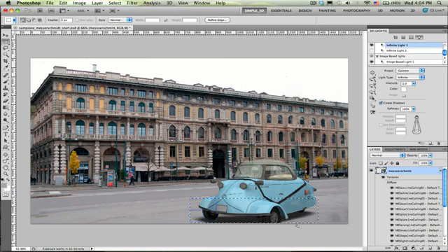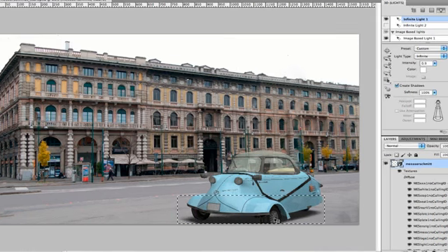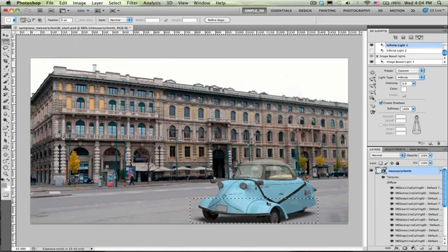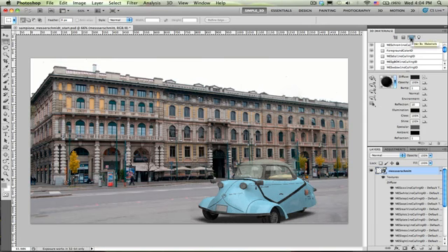Now the other thing that I want to fix for is the reflections. Notice that in this image, everything is reflective. The tires are reflective, the car is reflective, the roof, etc. And I want to change those properties. For one, I don't want my tires to be reflective. That's not very realistic. So up here, in my 3D panel, the third filter is my materials tab, and it's going to filter and show me all my different materials.